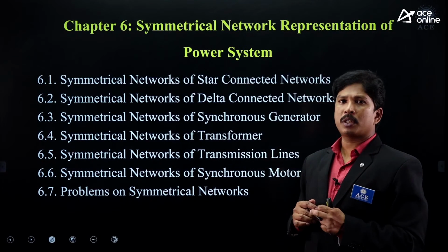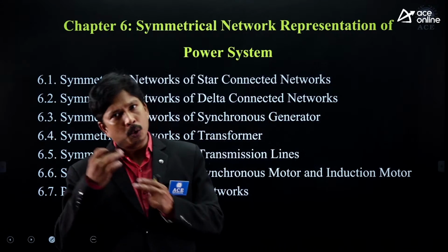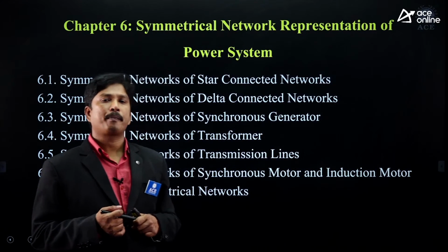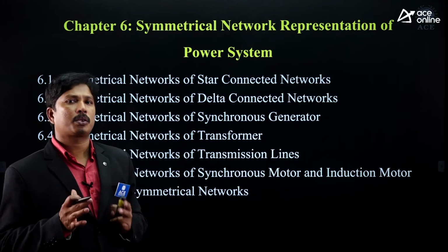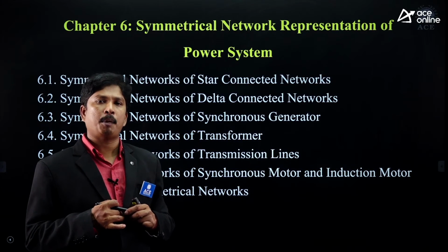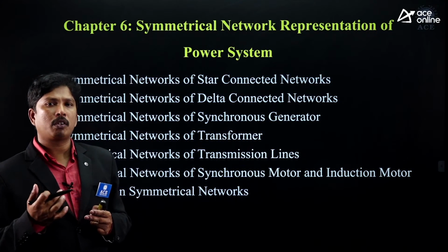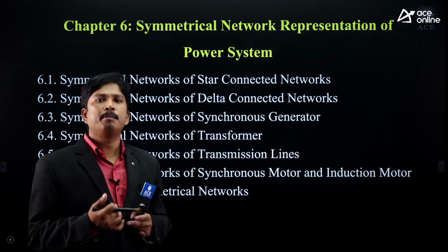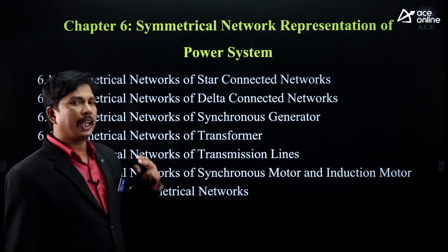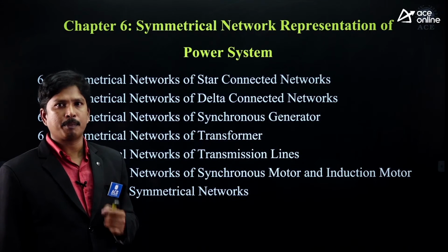It is one of the most important chapters, but still we are studying this chapter to go for the fault analysis only. Whenever you want to solve any problem in fault analysis, it may be any fault: single line to ground fault, double line to ground fault, double line fault or symmetrical fault, we need the symmetrical network representation of the individual power system networks.